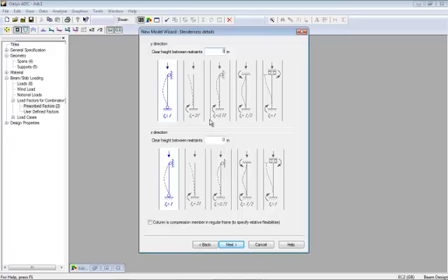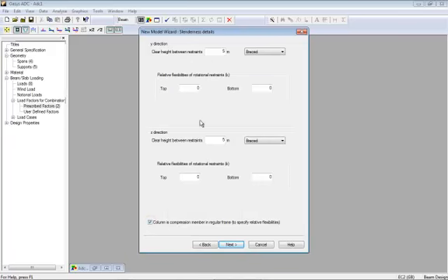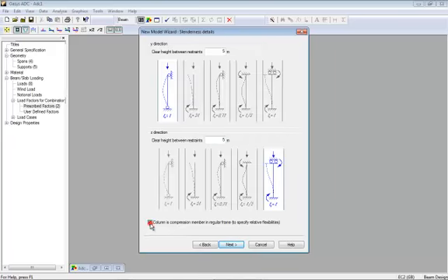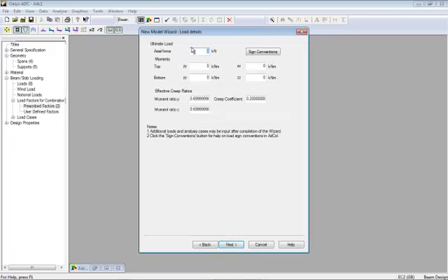If I just set these effective lengths, you can choose how the effective length is calculated, or alternatively you can go in and set it in a more detailed manner. Let's just take this option. Axial loads, let's say 3000. I'm going to leave the moments off because then you'll see how ADC adds the additional moments in automatically.